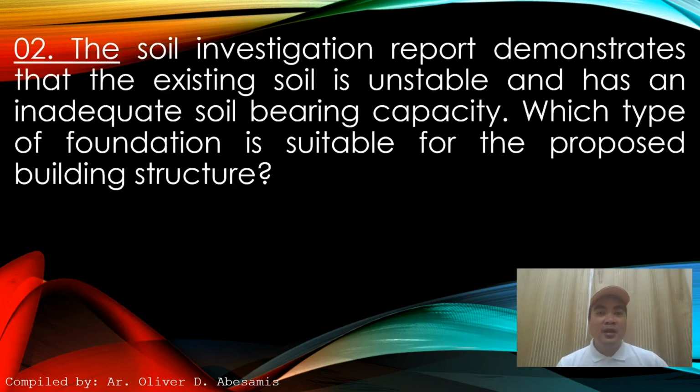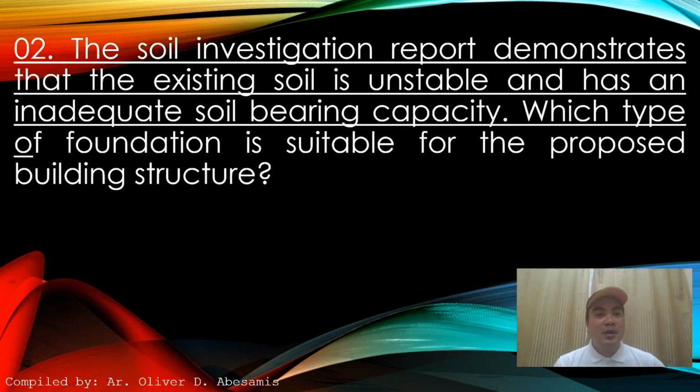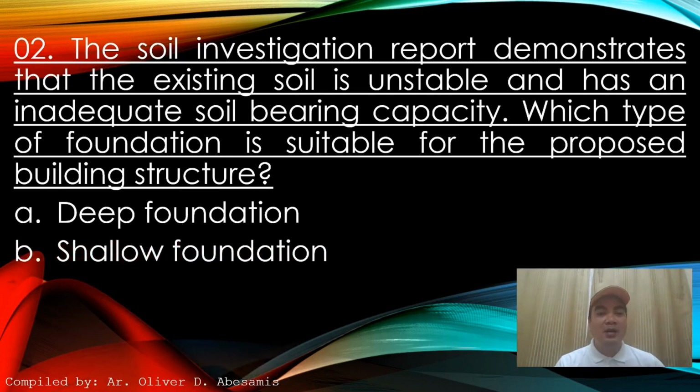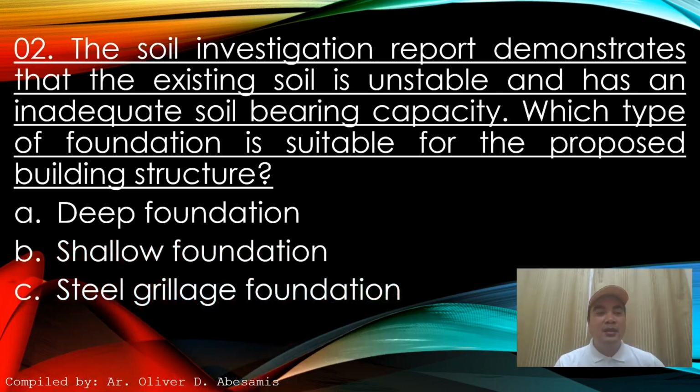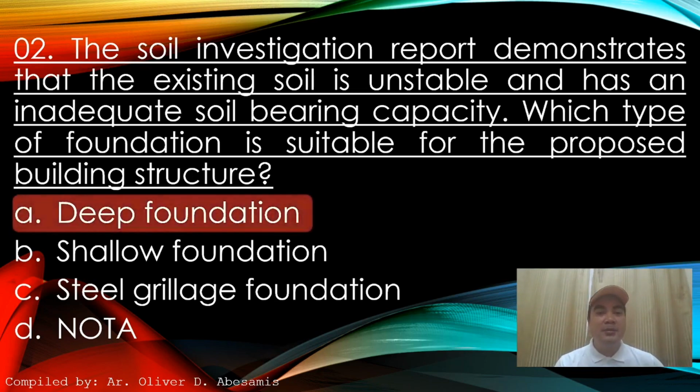Next, the soil investigation report demonstrates that the existing soil is unstable and has an inadequate soil-bearing capacity. Which type of foundation is suitable for the proposed building structure? A. Deep foundation. B. Shallow foundation. C. Steel grillage foundation. And D. None of the above. Answer? A. Deep foundation.